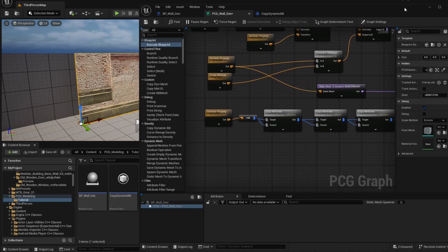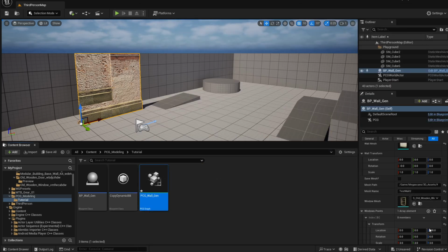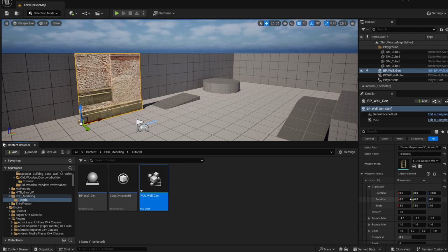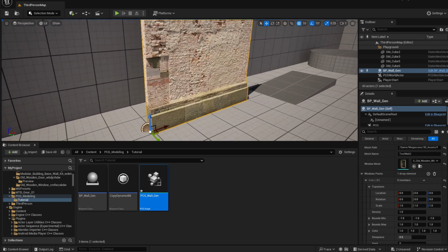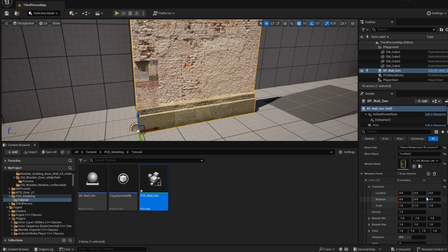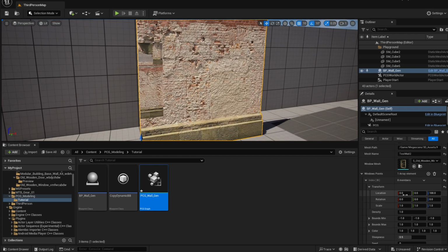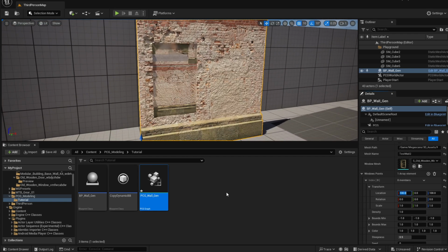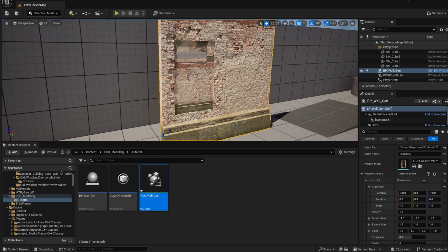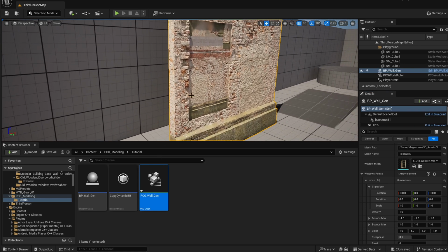The place is modified because we have a transform entity here. We also have a scale. That's the problem. Okay, so now if I have the scale set to 1, let's change the location, 100, 100. You can see I'm properly creating a box and cutting inside the wall. It's not cutting through the full wall.